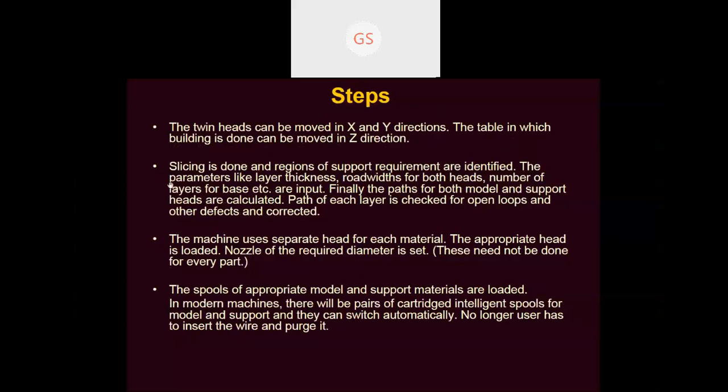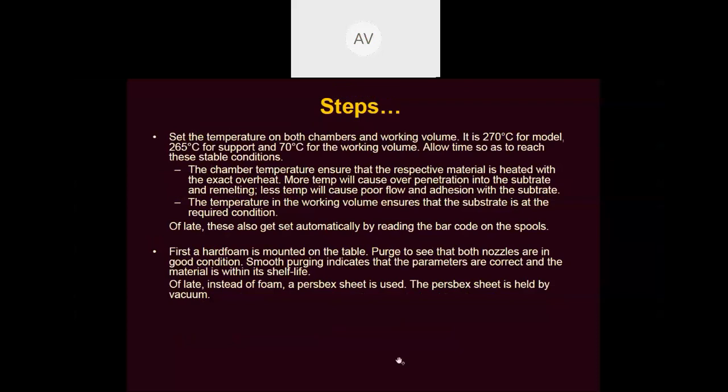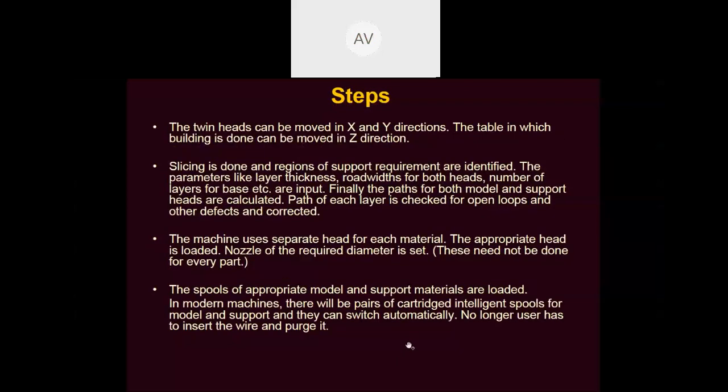Twin heads cannot be moved in X and Y direction. The table on which the building is done moves in Z direction. Slicing you can see. The parameter inputs, thickness and road width, are already decided by the system, by the software only.